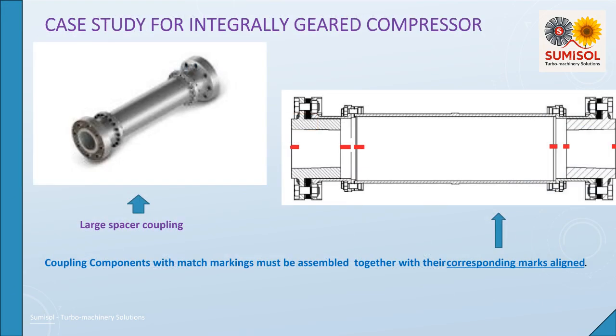It was found that the reason for the unbalance was mismatch in coupling set, and field balancing was proposed to solve this issue. Furthermore, it was understood that field balance would be at speed while shop balance is at a low RPM. Match marking shall be done by etching on the full set to eliminate any chances of possible error during dismantling and assembly in case any maintenance activity is carried out by operations in future.